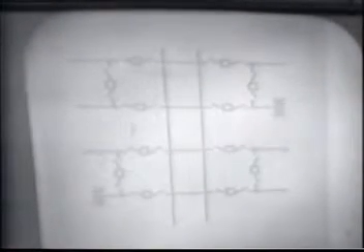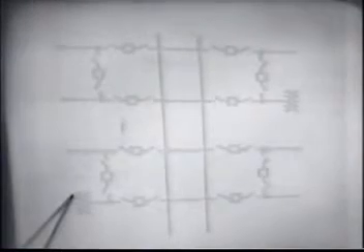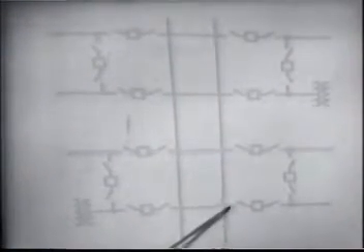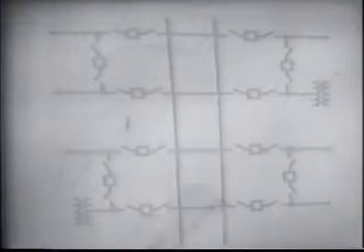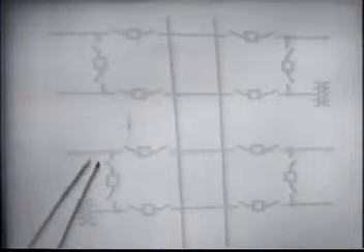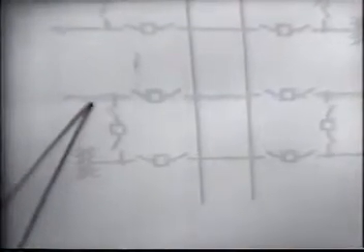In the breaker and a half scheme, you have two buses, and here again you will see this transformer or a circuit connected directly to one of the buses through a circuit breaker. Transformer in this case, this line in this case. And then there is a shared breaker between the adjacent circuits, the line and the transformer in this case.